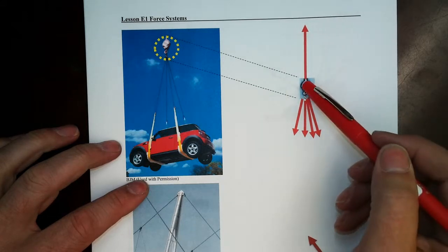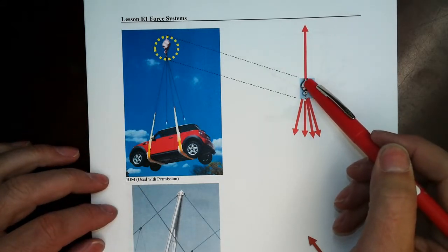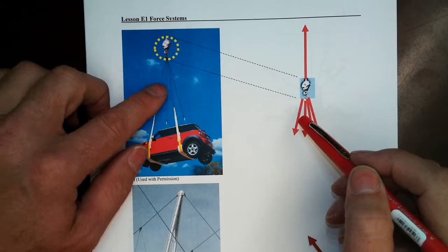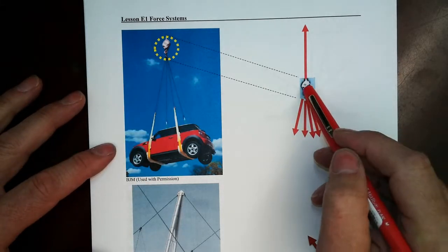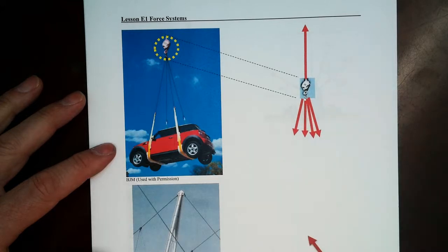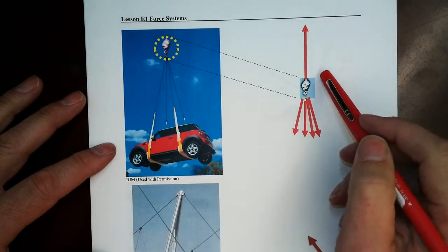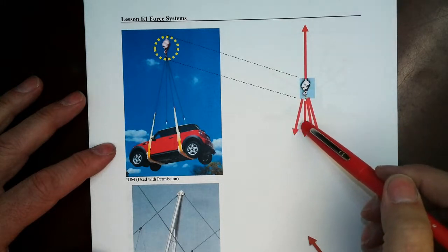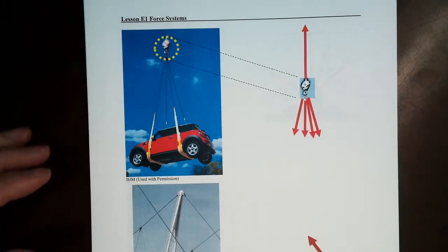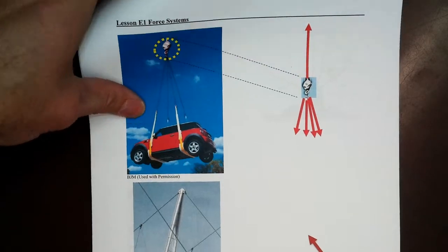The effect of that cable supporting that hoist hook is going upwards here, and then we have the four cables down there. Remember, cables and ropes only can go away from the body, so we have these four all coming out here. I won't give you the answer, but notice something about the geometry of all five of those force arrows, particularly their lines of action.